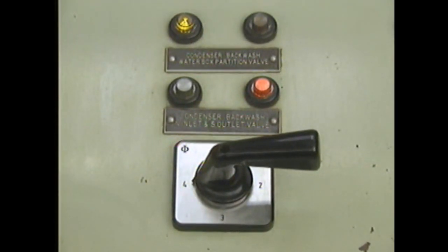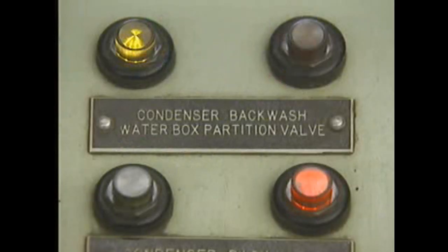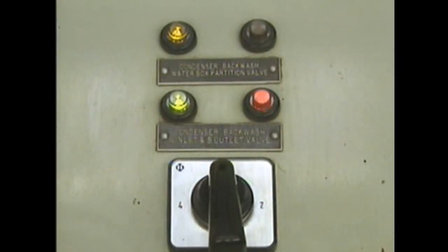In this setup, there are 2 valves and 2 motor operators. Each valve has 2 indicator lights associated with it. If valve operation is normal, but one indicator doesn't light, the problem might be the indicator lamp, or it might be the wiring. If the valve doesn't operate normally and one of its 2 lights is out, the problem might be in the motor operator's limit switch or in the switch wiring. The switch might be out